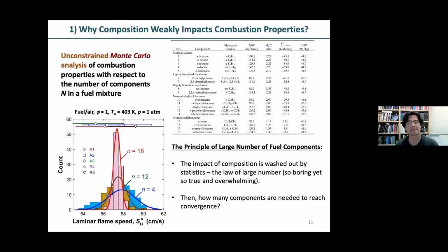Those of you who have measured the flame speed, and when I go talk to Professor Fokion Egolfopoulos, Professor Ed Law, they will assure me that they will not be able to measure the flame speed to that accuracy. Okay, in other words, what I show on top is a cluster of data under the conditions shown for jet fuel and for rocket fuel. What you can see is that the symbol corresponds to the flame speed under that condition, and the error bar represents the measurement uncertainty. So what I'm seeing here is something that's very simple. When you get to a multi-component mixture, as long as you have a sufficient number of components in this mixture, they are all going to behave the same.